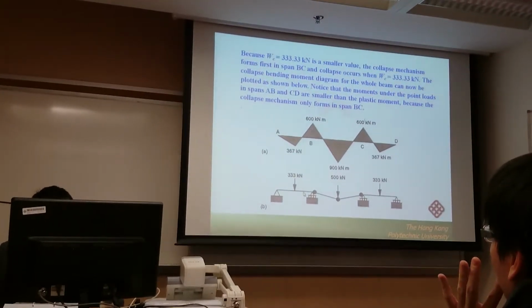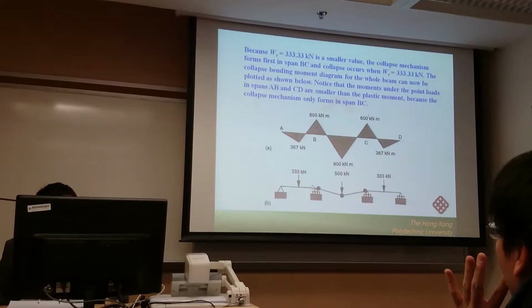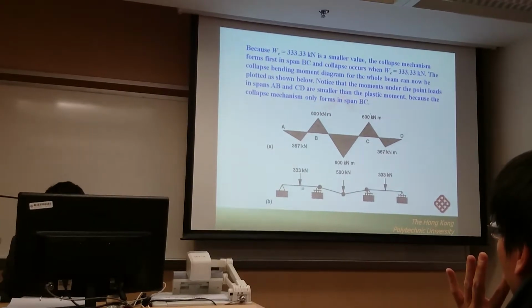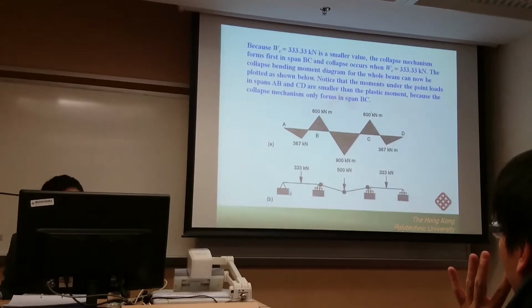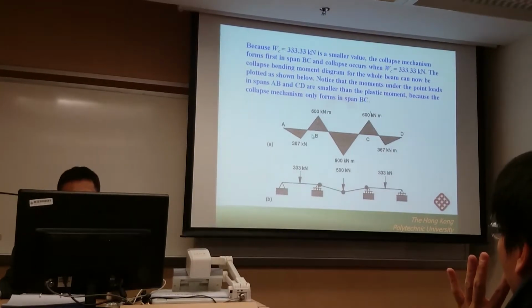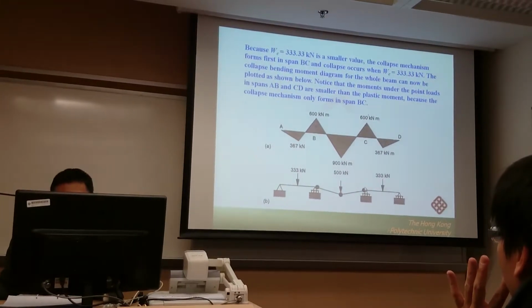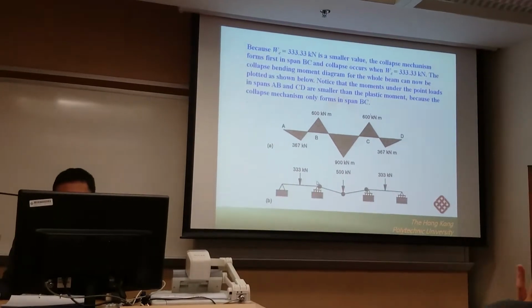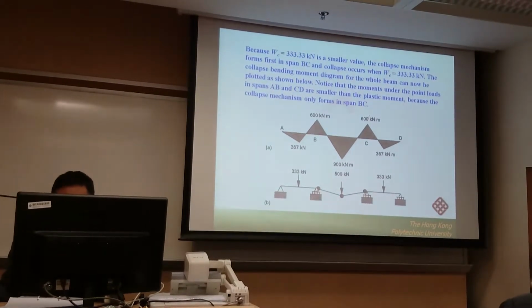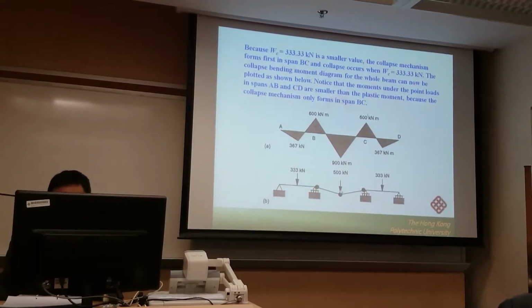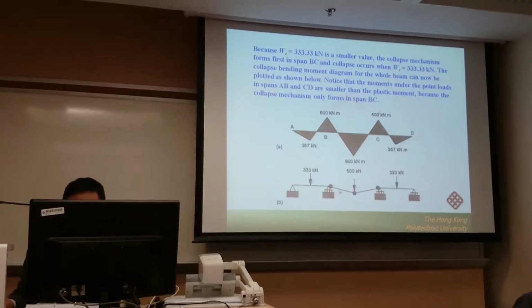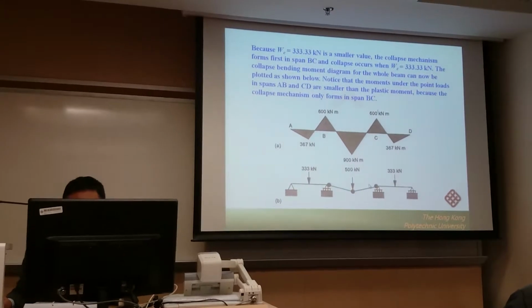So this is a simply supported beam, subject to external force and applied moment. So we are always able to obtain the moment diagram. And similarly for the internal span, you just need to apply the moment at the two ends and also apply the force, and then you can obtain the moment diagram for this simply supported beam.